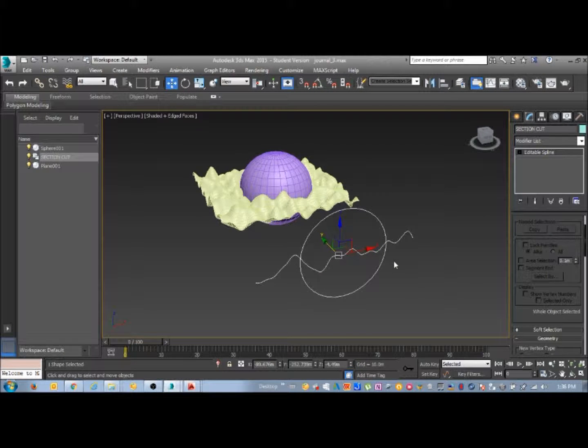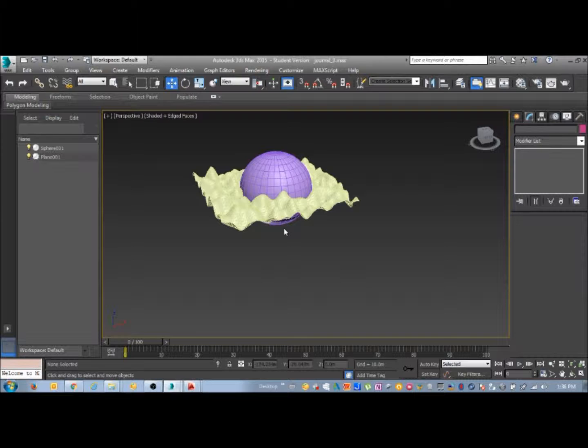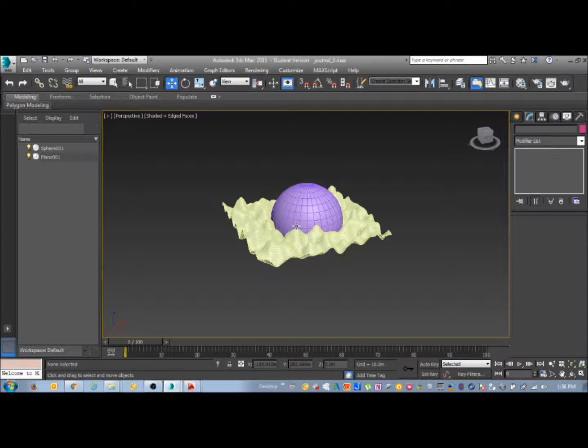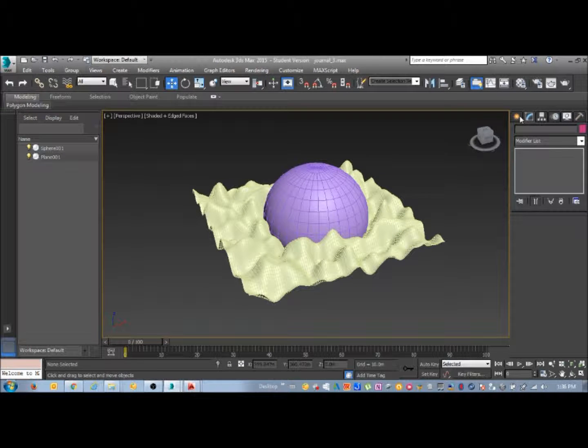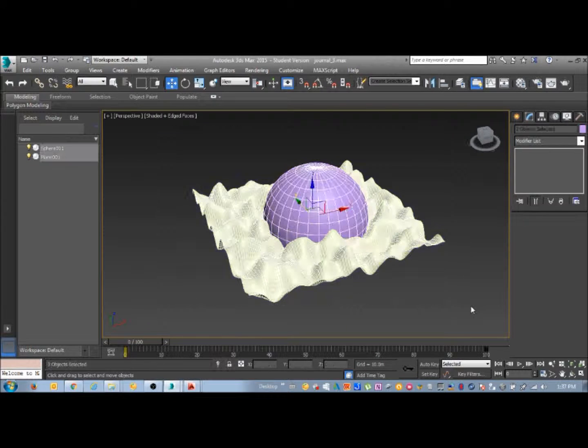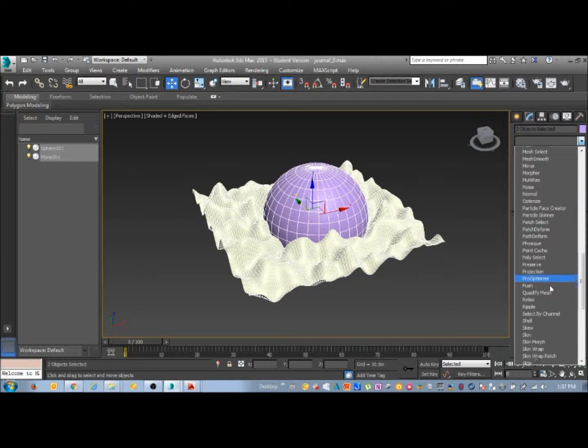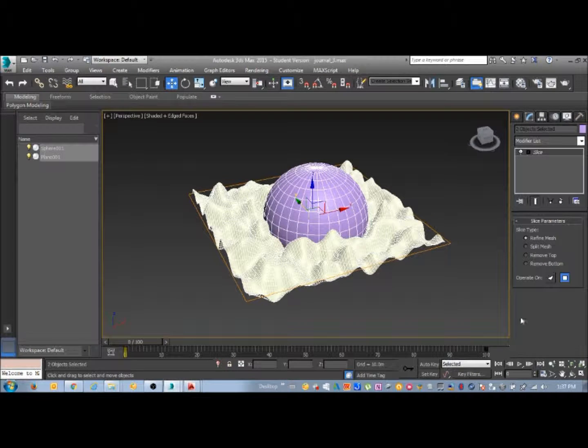There is also a second way to create a section cut, and this is using the slice tool. So this would be quite good if you want to do a sectional perspective or something which you want to render. So to do this sectional cut, we select our geometry, select everything, and go to the modifier. We're going to add a modifier of a slice.